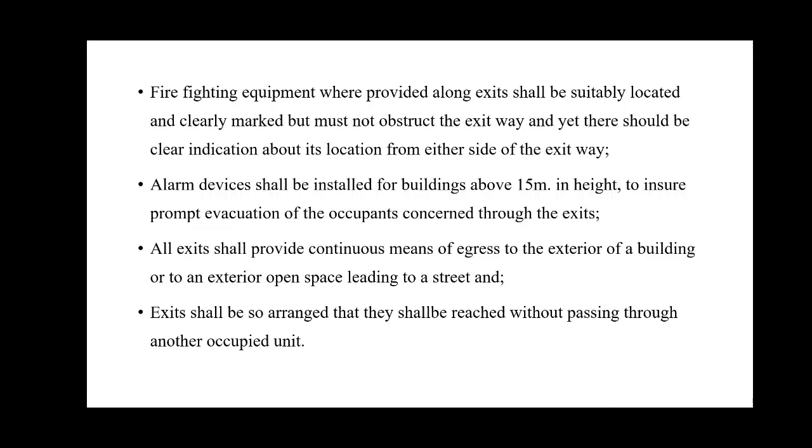The firefighting equipment which is being provided should be suitably located and clearly marked and should not be obstructed in the exit way. There should be a clear indication about the location from either side of the exit way. The alarm devices shall be provided in the buildings with the height of more than 15 meters to ensure prompt evacuation of the occupants concerned through these exits.